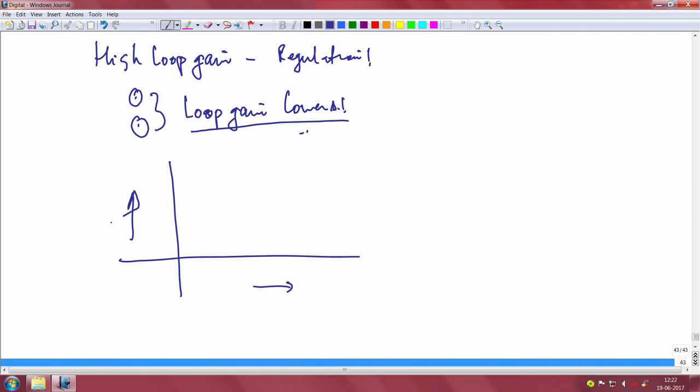It turns out the ability of the error amplifier, the LDO, so this is essentially the PSRR expressed in dB, okay. This is minus 70, this is minus 60, minus 50, minus 40 and so on. The deeper the better, right.